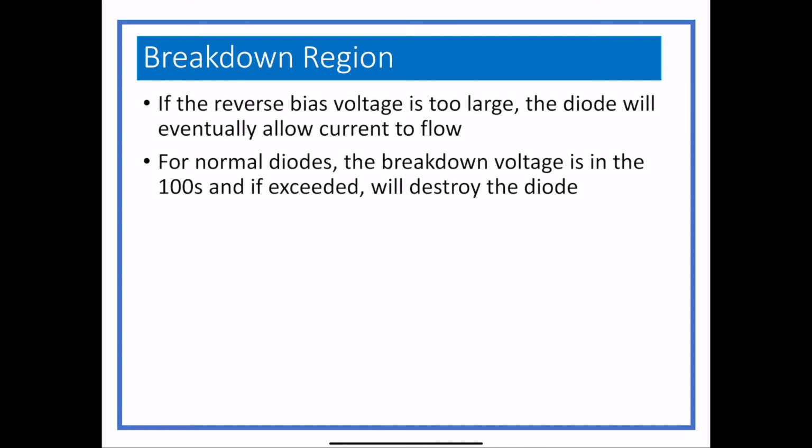If you get your diode to where it has broken down, what happens is the current flowing through it becomes instantaneously too high, and then you get heat, and from heat you get more charge carriers, and from that you get more current, and from the current you get more heat, and that's basically known as avalanche breakdown, and it burns up the diode. So it's a bad thing. And you smell the diode, yes. That smells bad.